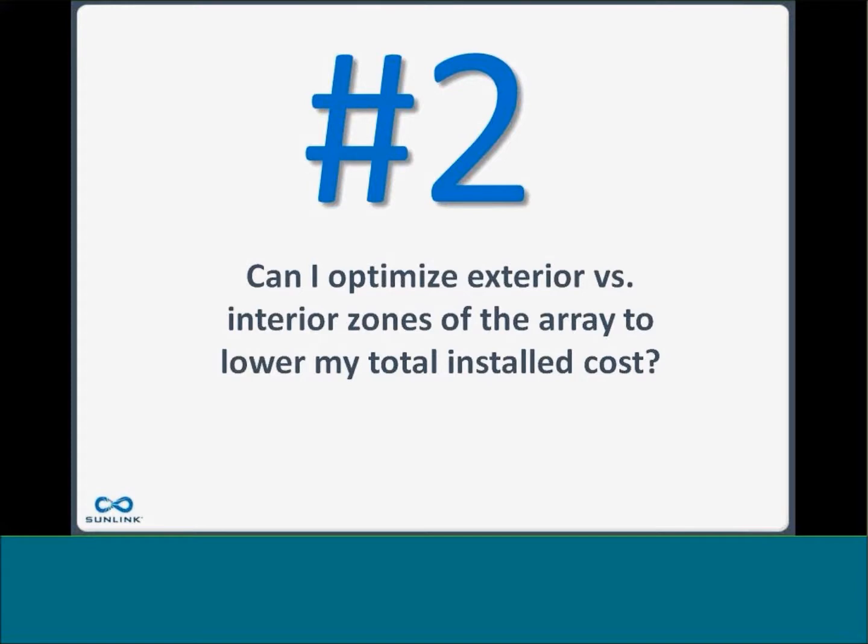For instance, a rocky or cobbled soil is very challenging to drive posts, and so your post installation price will increase significantly if you have to drill and drive, or if you have to grout around your post. Usually, because your per post price is so high, by increasing post spacing and minimizing the total number of posts on a project, you can really save a lot of money on those types of projects.